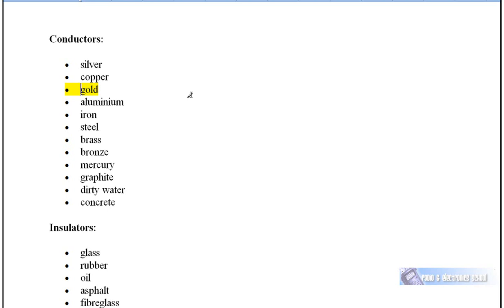And another very good example is a resonant cavity used by radio amateurs on repeaters, which is basically a high Q tuned circuit. The inside of the cavity is usually plated in a very good cavity with either gold or silver. Silver is the next best conductor on this list compared to gold, and it's a little bit cheaper than gold.